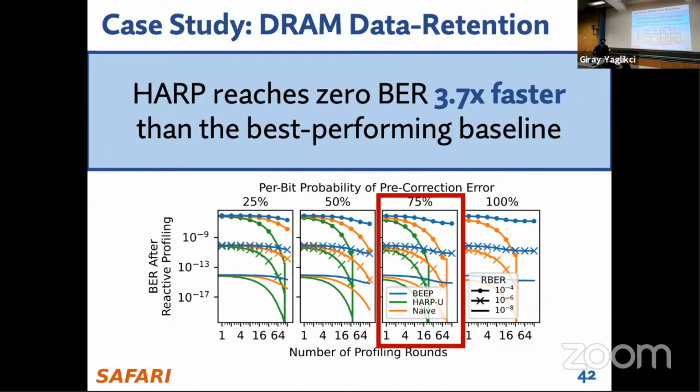Then the question comes up, is it even something you should be dealing with using profiling, or should you have some other mitigation mechanism that doesn't rely on profiling? Between those two concerns, it's such a big space in the error mitigation world to figure out what's right and what's feasible. What we're demonstrating here is that by being aware of the on-die ECC and making the changes to bypass it, as we described, for this case it does become much easier. But I wouldn't try to argue that it is feasible or infeasible either way.